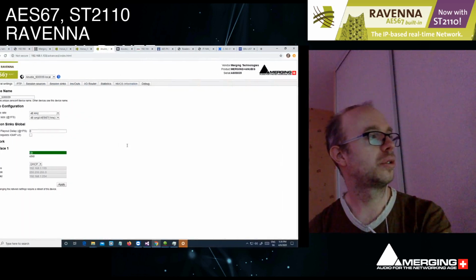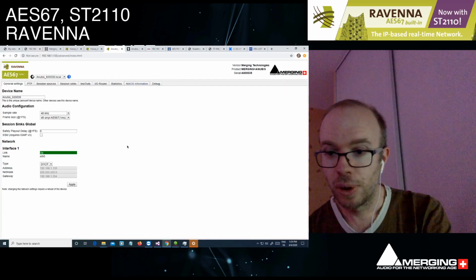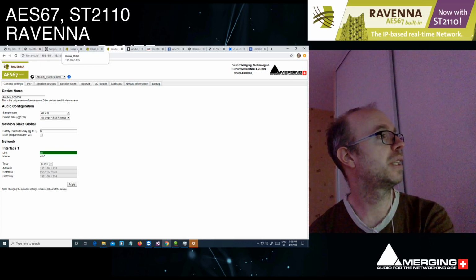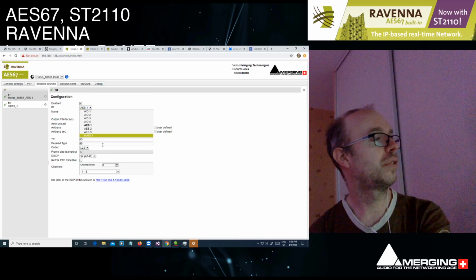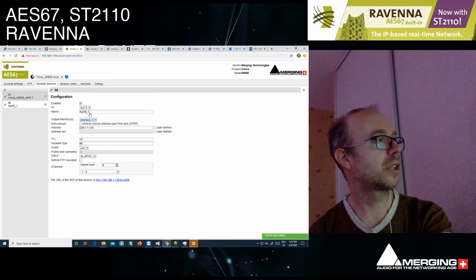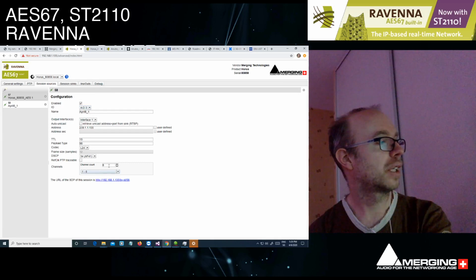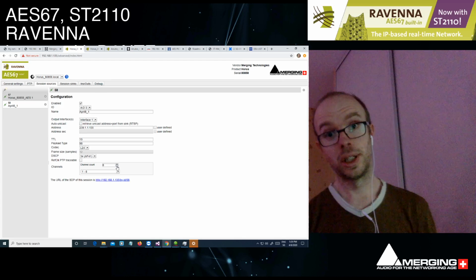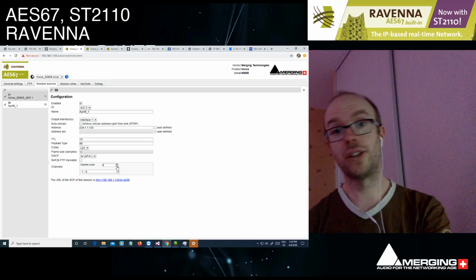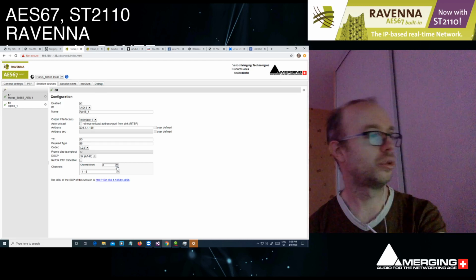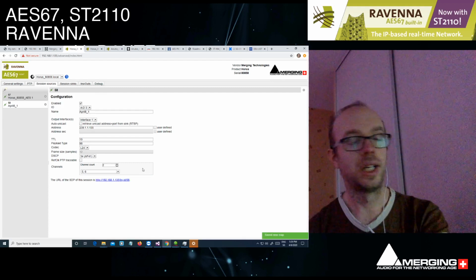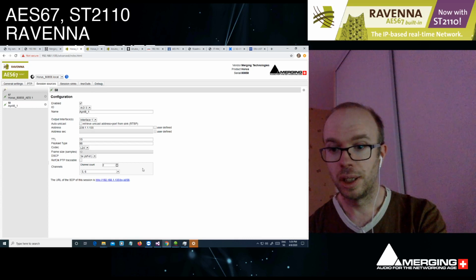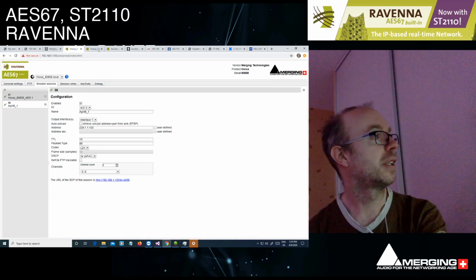So getting back to the demo to answer the questions from Tibor, the audio port on the source. Be it on the source or the destination, the audio ports are selected here. So here you choose one of the inputs, for instance, the analog to digital card number 3. It's an 8-channel card. So if I send the whole 8 channels, nothing special to do. If I want only to send 2 channels, I can select the pair here, for instance 5 and 6, and I click to apply. And this is how I select. I think this is your question.